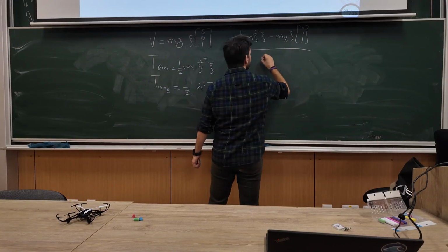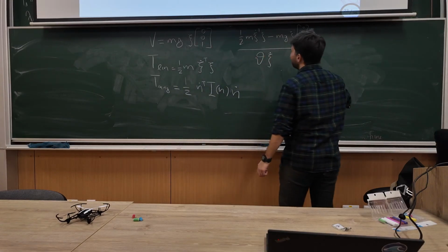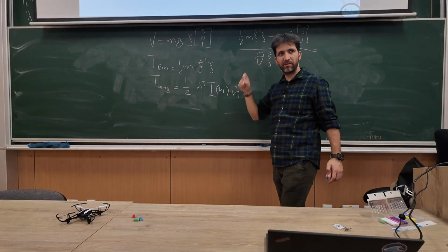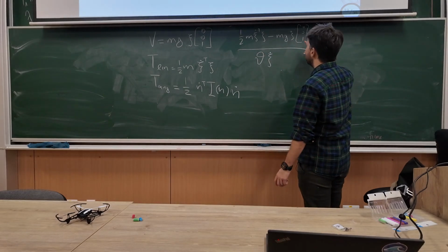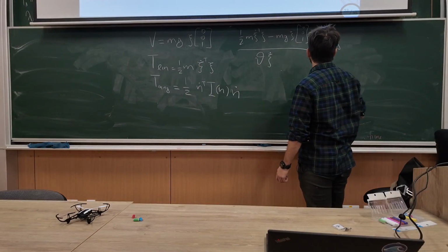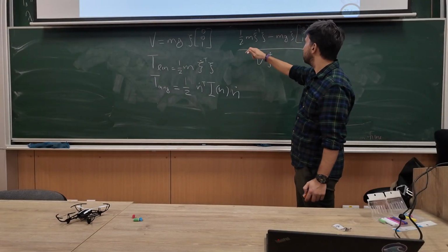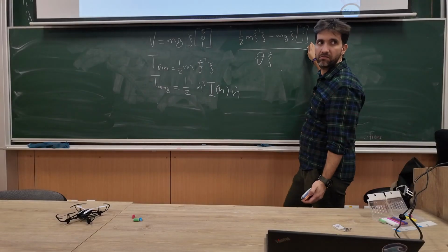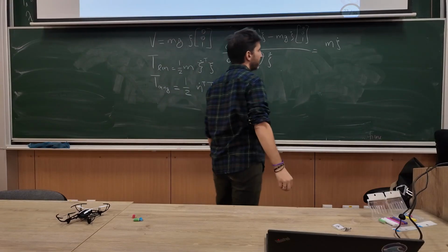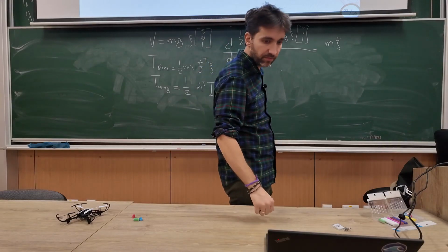The derivative with xi dot will be 2 times, because this is kind of like a square. We did a derivation in the dynamic modeling part. Basically, this will end up with 2 times xi dot, right? This xi goes away, and the 1 over 2 goes away, and then this will be 0, right? And if I take the derivative of this with time, I'll basically add 1 more dot, so I get the acceleration.